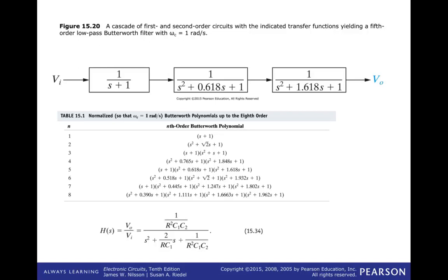At this point, you will take all of your R, C1 and C2 values and you'll scale those using a scaling technique, the same scaling technique that we used in the past. First to match your frequency and then to match any component values that you have to meet.